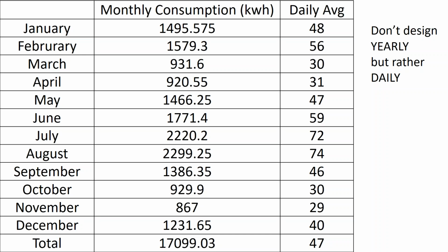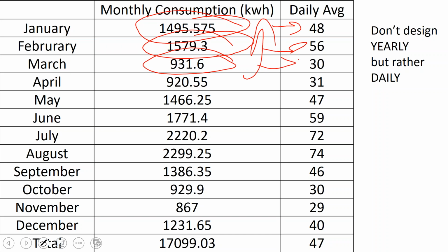You know, in Mississippi, we have a lot of wood resources, or in the solar industry, we would call it surface carbon rather than subterranean carbon. But we're making some major appliance changes, and I'll show you how to model that. After we adjusted his current consumption of his existing home for the fact that the new home is going to be more efficient and have less electric-intense appliances, what we got was a month-by-month printout of how much energy he's going to use over the given month. And we converted that into a daily average per month.